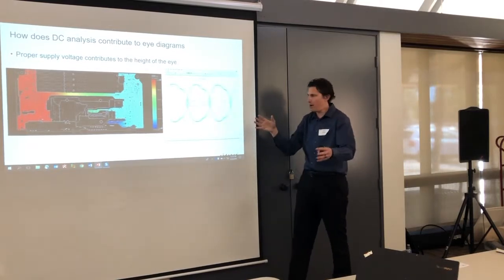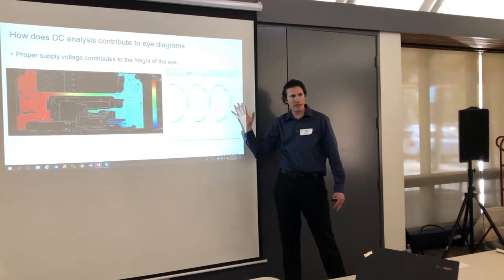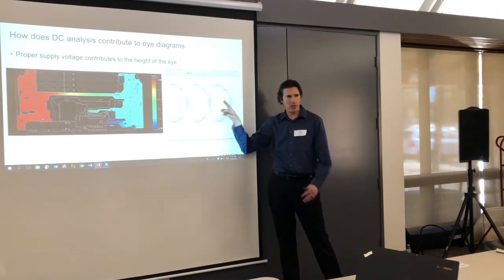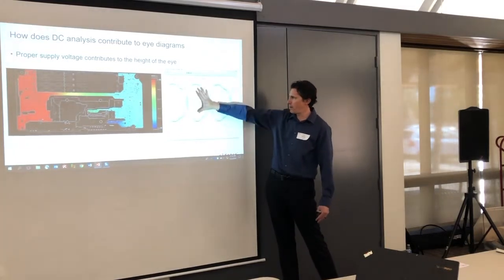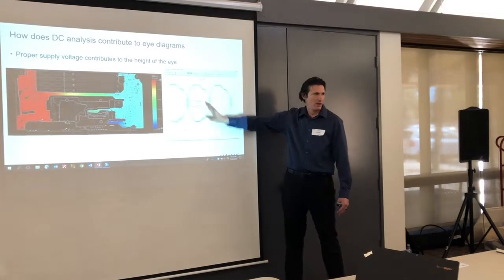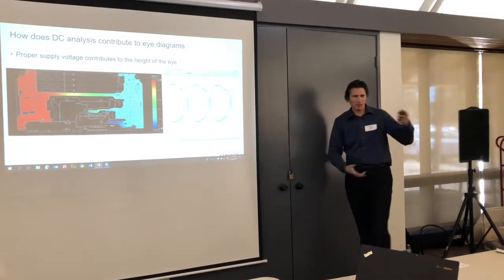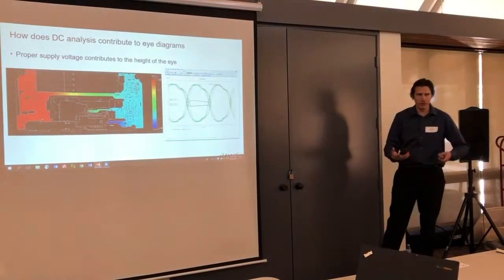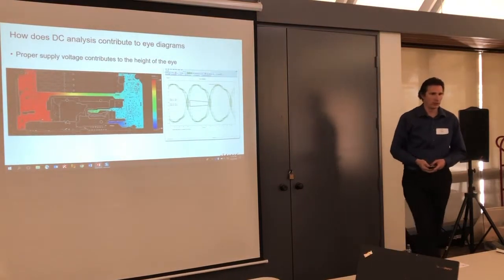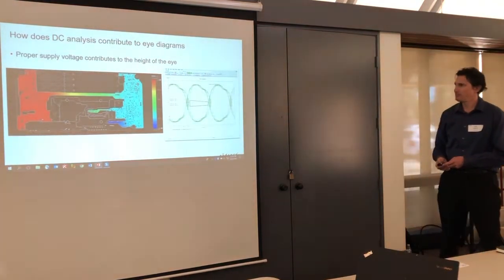So you can have compound problems of data coming early, data coming late, impedance and reflection shrinking that eye this way, and bad voltage and noise shrinking that eye that way. All these little things that your SI people are constantly asking you to take care of and deal with, this is their ultimate goal of what they're trying to accomplish, more or less.